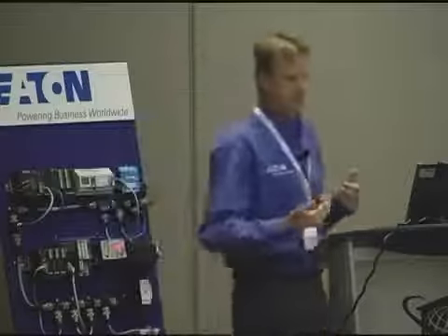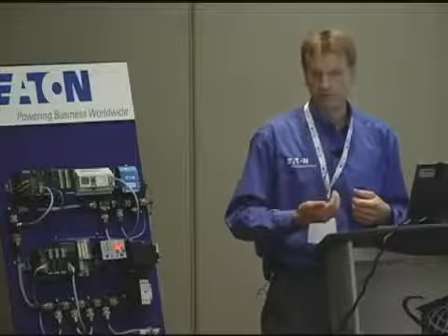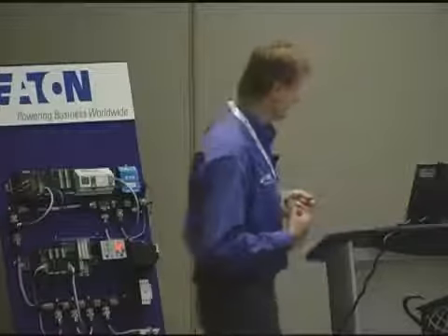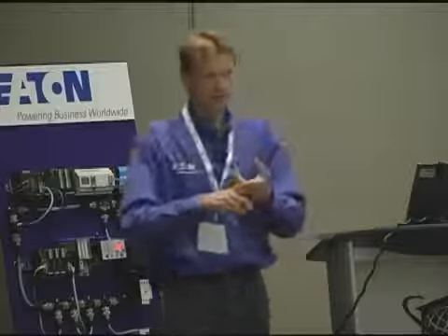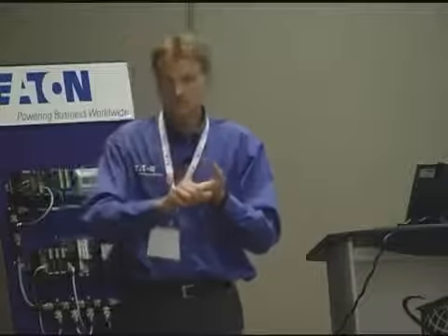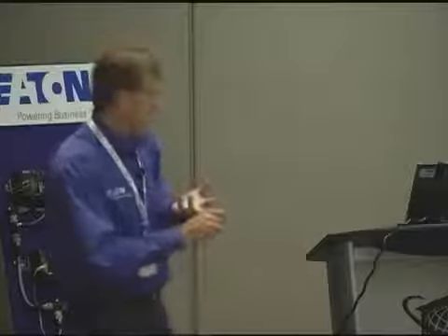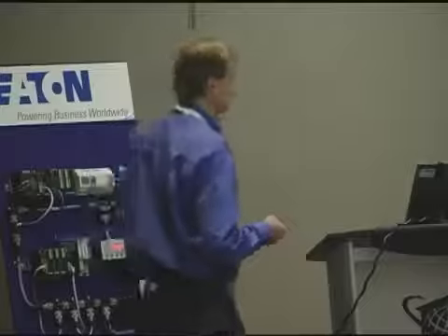You may have to look at the technical capabilities in your company when deciding which network to go with. As well as troubleshooting tools, hardware tools. Are there any media checkers? So a network goes down, now what? I don't know, start changing cables, or maybe put on a device that tells you you might have a break in a wire somewhere. Okay, software tools: protocol analyzers, a way of configuring devices over a network, a way of testing devices over a network. Are those kinds of software tools readily available?